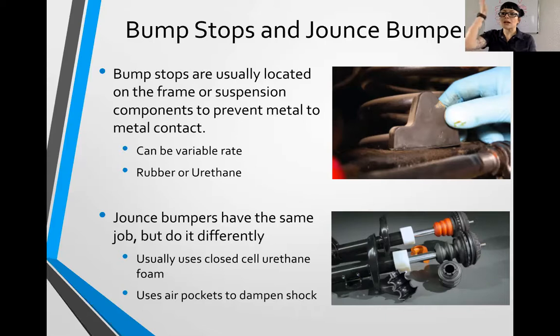And so you may not get a loud thud. If I hit the bump stop on my suspension or frame, I may get a loud thud. It won't be a clunk, but it'll be a thud, and you're going to definitely feel it inside the vehicle. It's sort of rough. Jounce bumpers are a little bit softer, which is why they're a lot more commonly used these days.